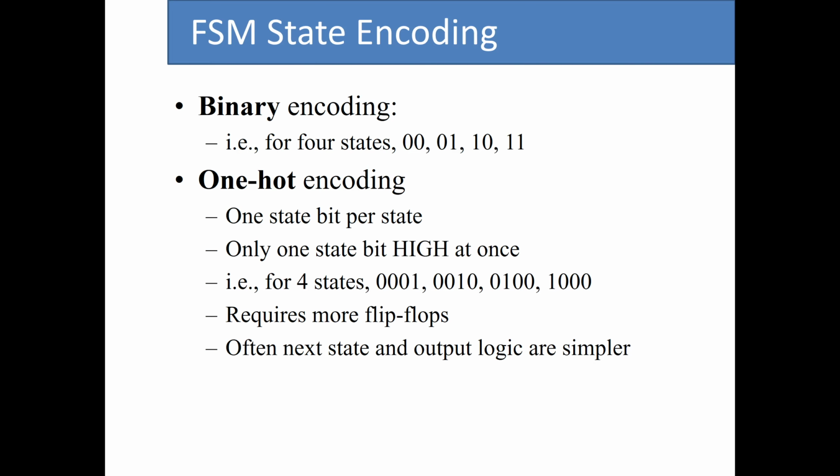If you look closely, you cannot switch different steps. So you cannot come up with the encoding before writing the state transition diagram, right? As for the encoding, for this specific example, we just said that we have the state and we use the binary encoding. So let me write this again one more time. We said we have S0, which we make equal to 00, S1 is 01, S2 is 10, and S3 is 11.